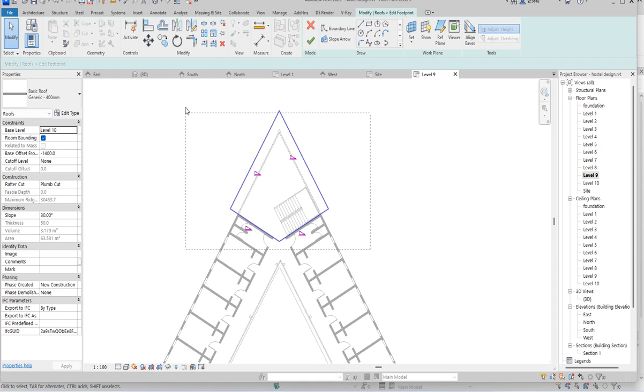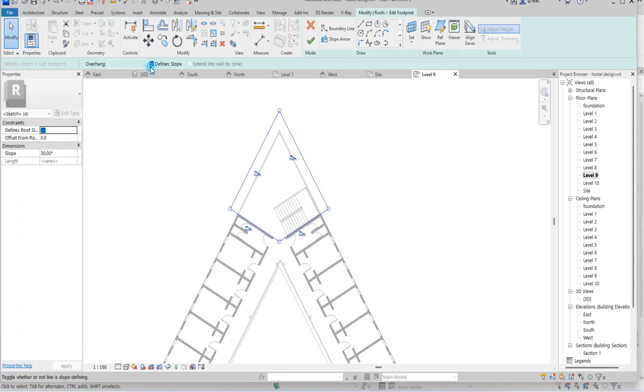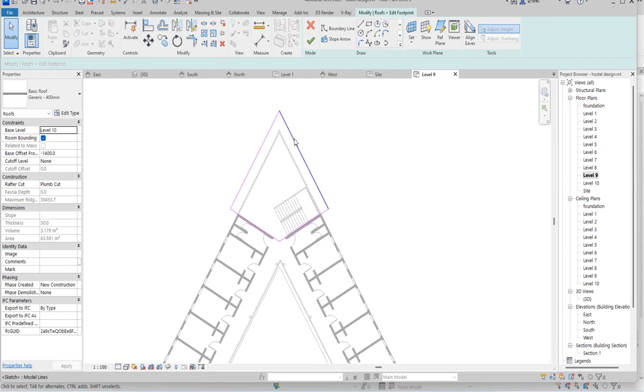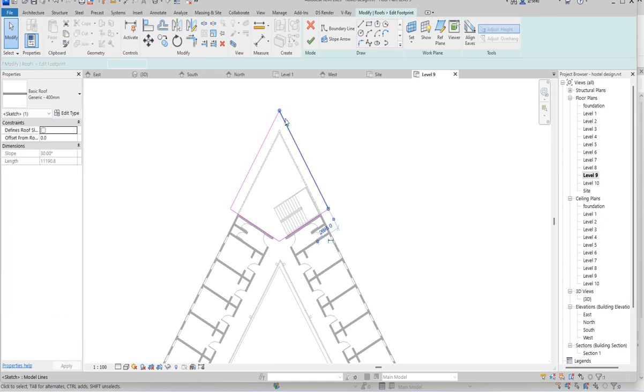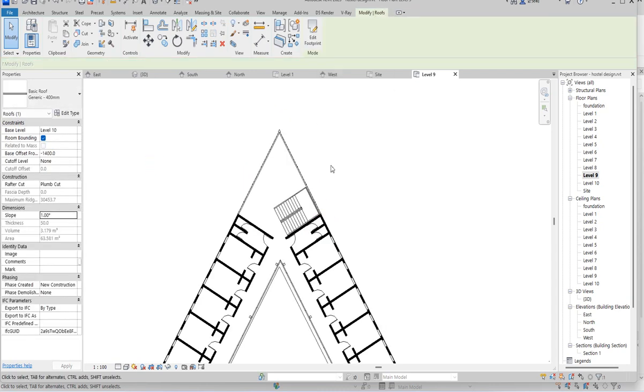So I'm going to select this and say define slope. So what the define slope that I'm having here is that this one is going to be thoroughly flat. So what will I do? I'm still going to use the same thing. So instead of using 2 here, I'm going to use 1 because I don't want it to have any appearance of anything at all. So I'm going to click here and I say 1. It's my define slope. So click here, it's going to appear completely flat.